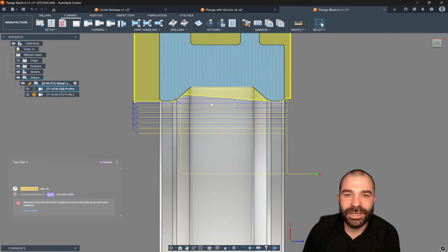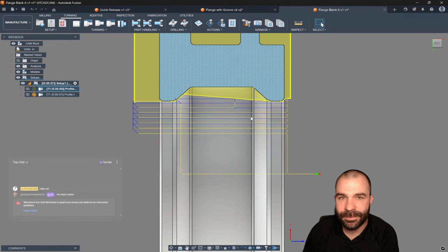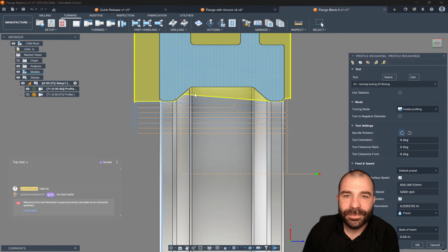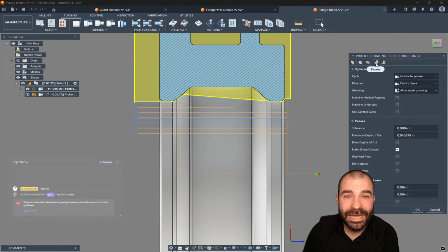And then as you're going to see, we're now boring out the entire inside part of that slug, right? But this is, again, where I need to say: don't do this. It's a bad habit, and it's hard to break. Don't just jump over here and turn off groove, right?